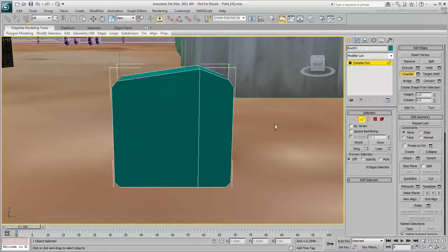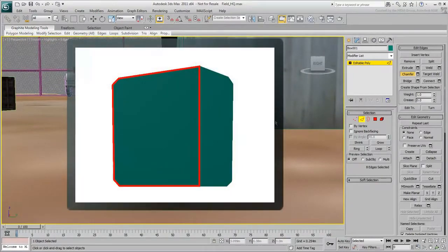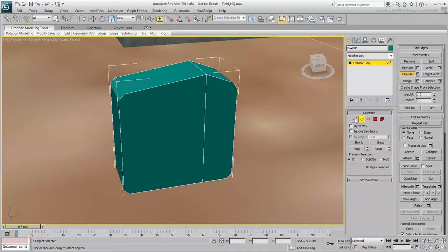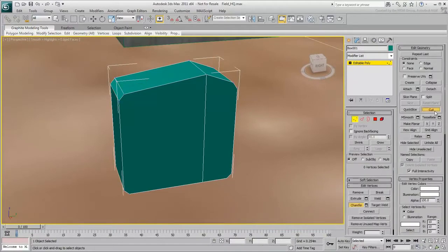The corners look good, but chamfering created 6-sided polygons, which can be a problem. 6 is an even number, so you can divide each 6-sided polygon to obtain quads. Select the vertex sub-object level. Turn on Cut mode. Place the mouse directly over this vertex. Make sure the correct mouse icon displays, and click to mark that vertex as the start of the cut.